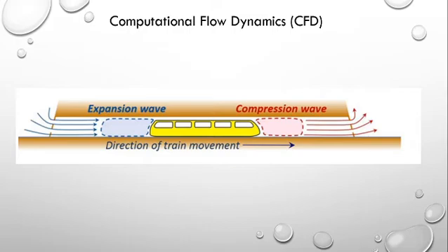Now in underground systems that's fine because you've got a station every 3 or 4 miles, which means that air's got somewhere to go, it's got somewhere to vent to. But if you think about the Channel Tunnel, it's about 35 kilometres from one end to the other, and that air has got nowhere to go. What would happen if we couldn't get rid of that air is it would build up and make it more and more difficult for the train to pass through the tunnel.